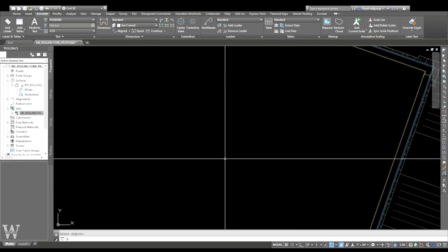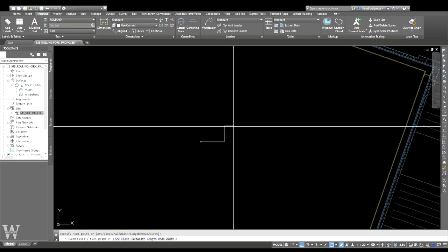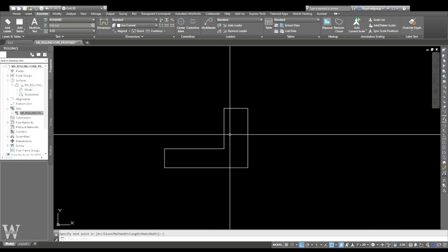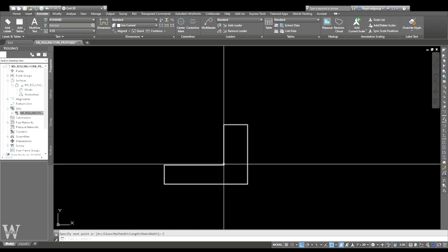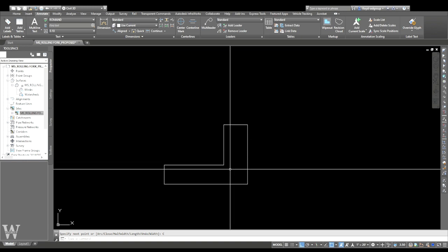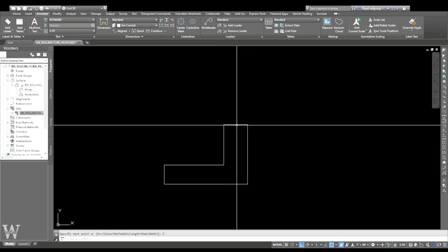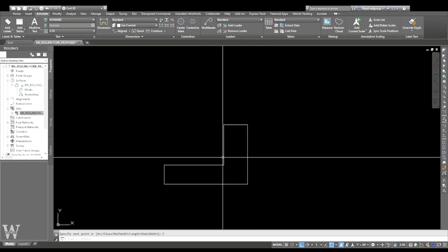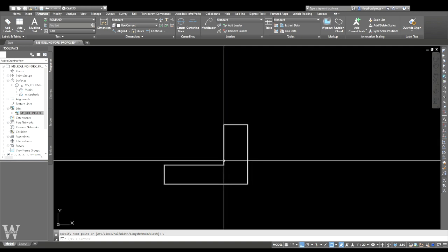One thing that you need to know about AutoCAD, Autodesk, and Civil 3D is that Civil 3D can't do vertical surfaces. What that means is if you want to put a wall in or a curb or anything that has an elevation difference from this point to that point, and there's no change in the X direction, it can't do it because it creates triangles, and they have to be 3D triangles, but they can't be in the same plane.